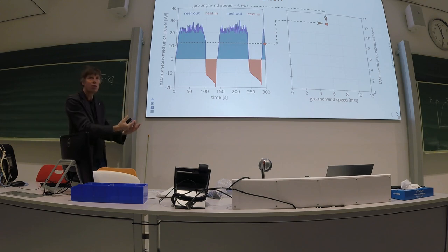if you accumulate all of this energy in a battery, and that comes out of the battery, and then you calculate the average power, you would get to this line. So of the 20 kilowatt that you harvest here, about 12 kilowatt remain on average. And the rest is here, the red area, and this one is balancing each other out. It's a bit of a simplified picture that I give you because there are also losses.